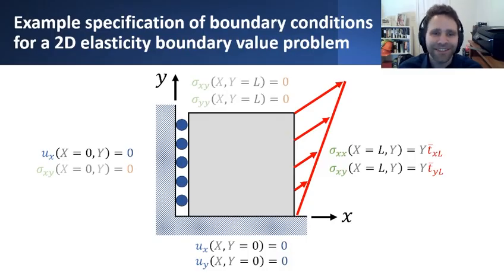And then on the left face, kind of a curveball for you, but the idea is I could prescribe a combination of both displacement and traction so long as they don't conflict with one another. In this particular example, I'm saying prescribe directly the x component of displacement by preventing any displacement in the x direction on the left end of this block.